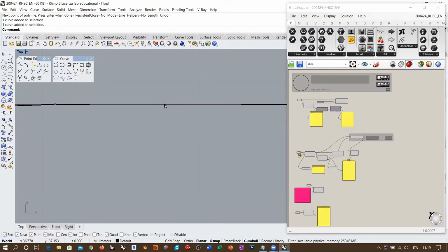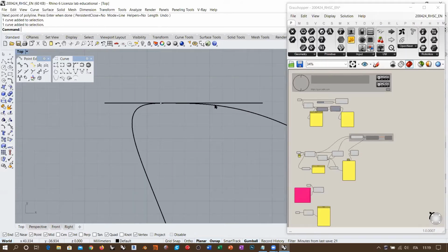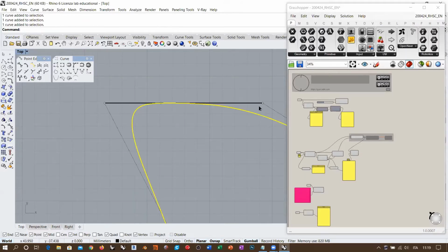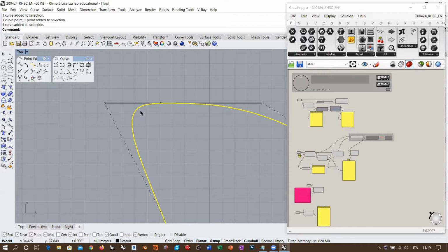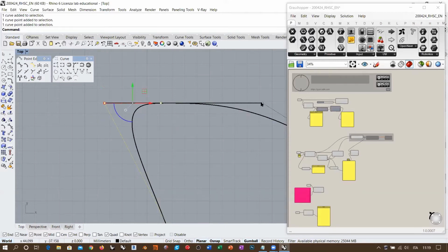I don't know if you already can guess what point this is for our NURBS curve, but this is a knot. So when I align 3 control points in a row for my NURBS curve, the contact point between the NURBS curve and the tangent line is a knot. So how can I make our NURBS curve pass exactly through this point here? Well, I simply have to make these 3 control points symmetrical with respect to the mid control point.